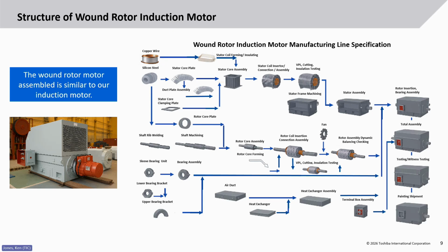And we'll get into the winding slot assembly here in a second, but it's basically banded on the ends to handle the forces and then welded across the surface of both the rotor and the stator to hold things in place.